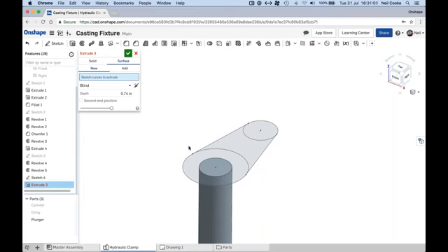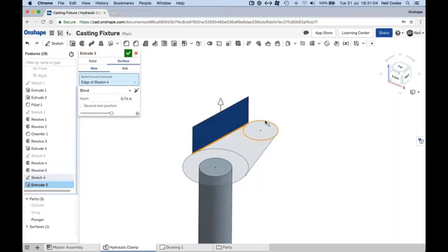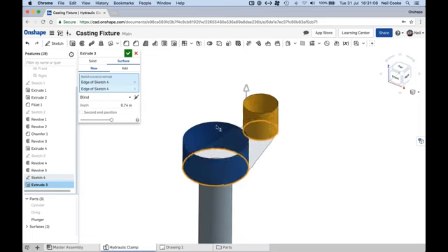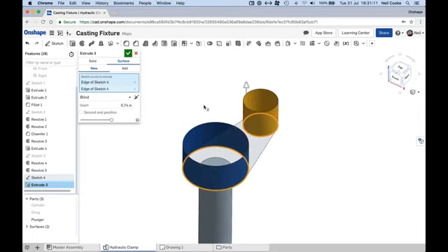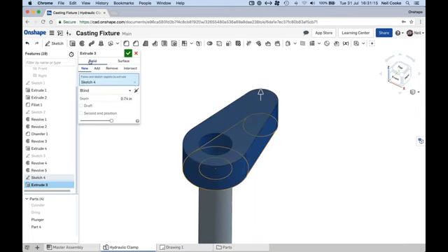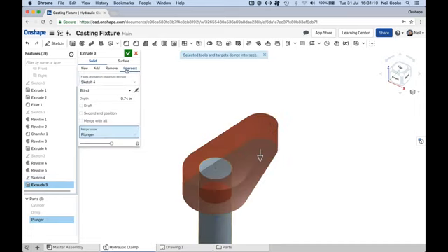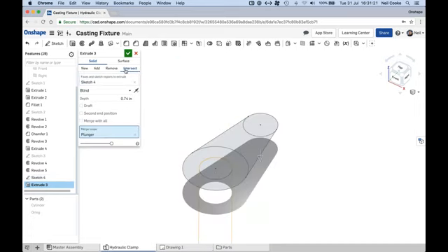Now, the reason that's disappeared is because Surface is expecting you to select individual entities. So, you might want to select those two, but essentially you're creating a surface from the same extrude command. Then you have solid, you can create new, you can add, you can remove, or you can intersect. So the intersect is like a Boolean intersect.